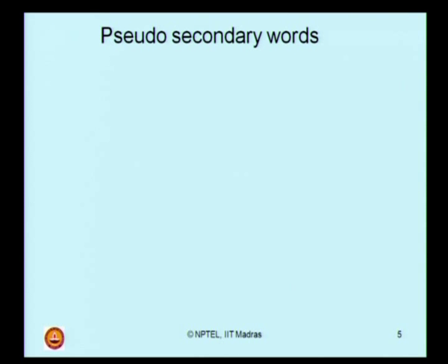Primary keyword talks about design intent and secondary keyword talks about deviation on that design intent. So, in a segment of a plant, you identify the design intent and try to locate the possible deviation of the design intent in the plant. So, couple these two together as primary slash secondary keyword in your Hazop report.